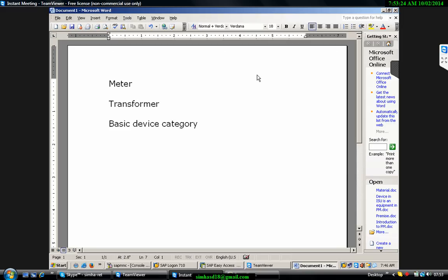Now, in order to create an electricity meter or a water meter or a flow meter, the most important element of that instrument or device is the register. We saw that the register is the one doing the basic job of counting. You need to keep the total cumulative consumption, and that part is done through the register. The register is the one doing the counting part. It can be a simple revolving wheel like we see in the traditional meters. It can also be something very advanced internally, which may give the output in the form of a digital number.